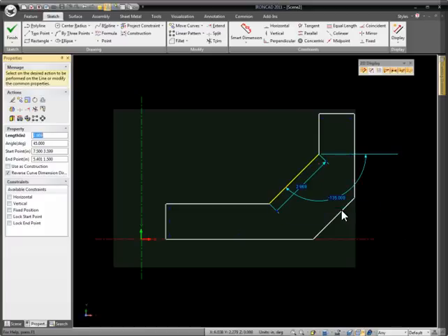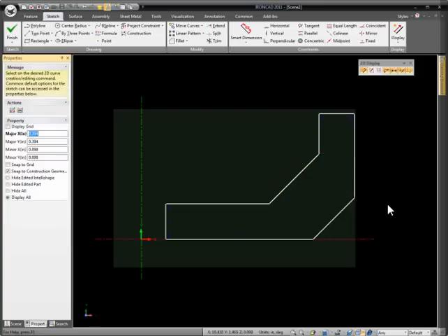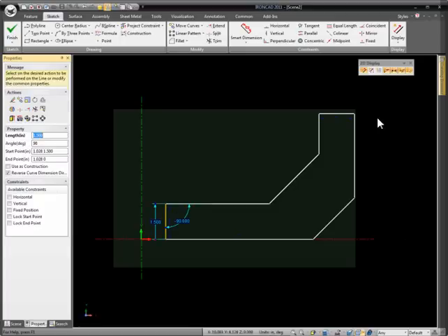If you hold the shift key down when you're dragging an angle handle and move your cursor over another aligned or angled line, it will snap automatically to that, and you can see the 135 or negative 45, if you will, automatically snap and align to that geometry. Now, as you can see, at this point we have this set distance to be 1.5 and our top distance to be 1.5. But how do we set the distance between these two lines? Notice we don't have a real easy way to do that.